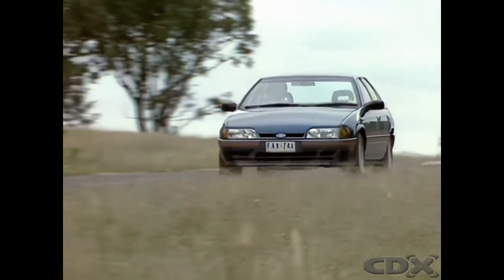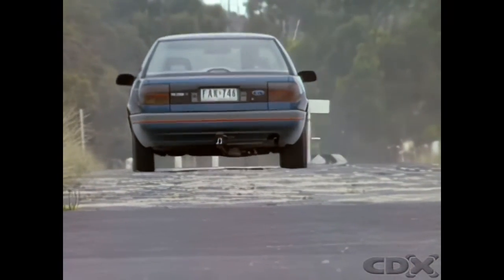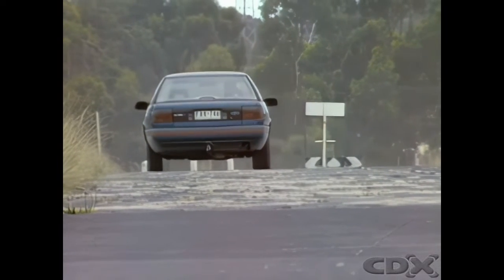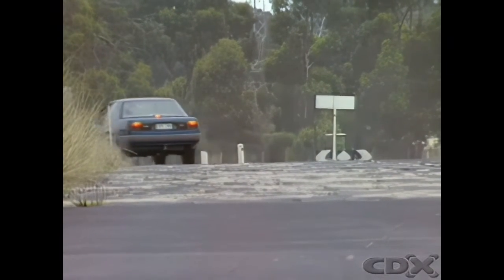A radial ply tire runs cooler than a comparable cross-ply tire. This increases tread life. Also, a radial tire has less rolling resistance as it moves over the road surface.